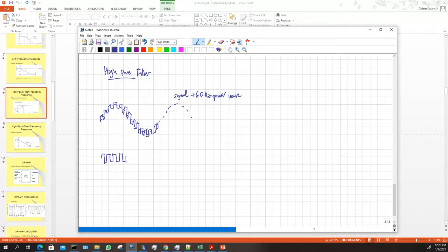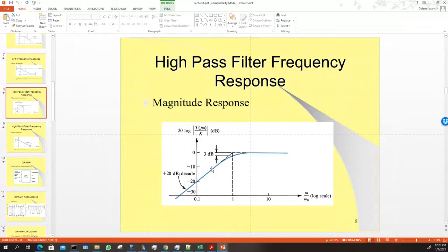So that's called a high-pass filter, because it passes high frequencies and eliminates low frequencies. That one looks like this. Again, this is a first degree, very basic high-pass filter. It passes the high frequencies, but for the lower ones, the gain goes down as you decrease your frequency. By the way, there's no zero here, because the x-axis is logarithmic, and it will get to zero at negative infinity.